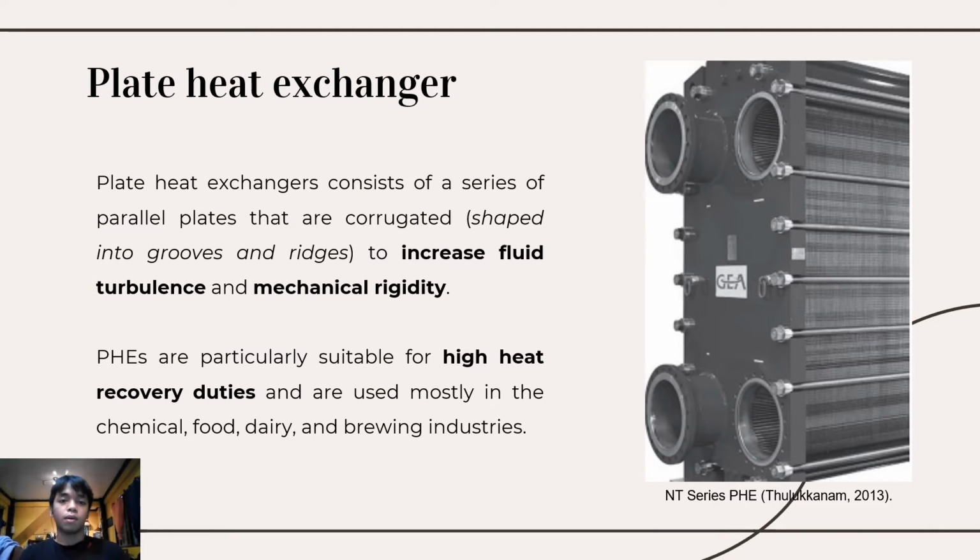Next, we will be talking about the plate heat exchangers. Dr. Richard Seligman, the founder of APV International, introduced the first commercially gasketed plate heat exchanger design in 1923. A plate heat exchanger, or PHE, consists of a series of parallel plates that are corrugated, both to increase turbulence and to give mechanical rigidity. Plate heat exchangers are particularly suitable for heat recovery duties in the chemical, petroleum, food, dairy, and brewing industries.